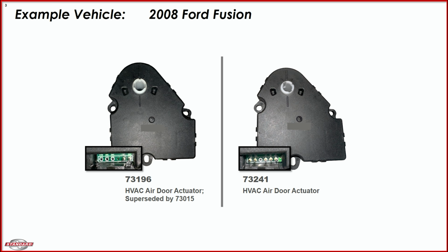It's always a good idea to go straight to the source, the manufacturer's schematic or wiring diagram, just to make sure you know, number 1, that you have the correct actuator, and number 2, that you know what you're looking at when diagnosing and recalibrating an air door actuator.